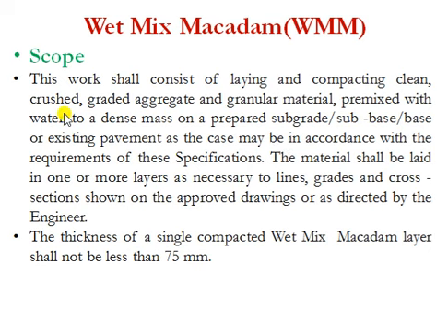So first let us see what the scope of wet mix macadam is. This work shall consist of laying and compacting clean crushed graded aggregates and granular material premixed with water to a dense mass on prepared subgrade or subbase or base or existing pavement, as the case may be, in accordance with the requirement of this specification. The material shall be laid in one or more layers as necessary to lines, grades and cross sections shown on the approved drawings or as directed by the engineer.